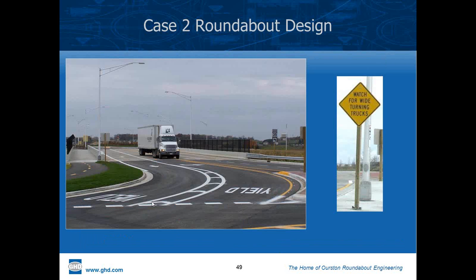And that's typical of the case 2, a 4 to 6 foot hatching area. So it creates some lane discipline approaching. And it's been found necessary to apply signs like this in British Columbia. They invented a sign with more of a diagrammatic look, showing the car and the truck pinching. This one just uses the text for now. And in time, it'll probably move to the symbol.